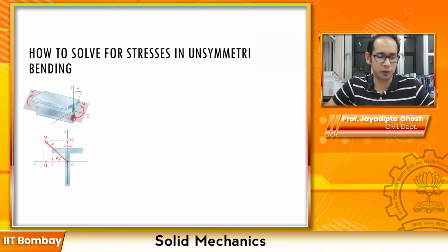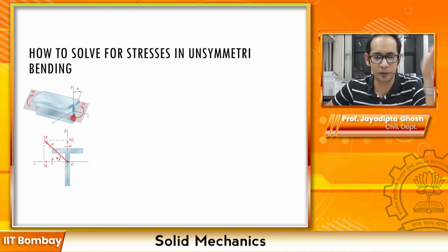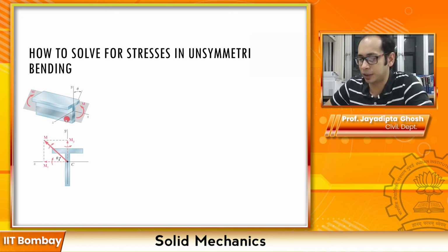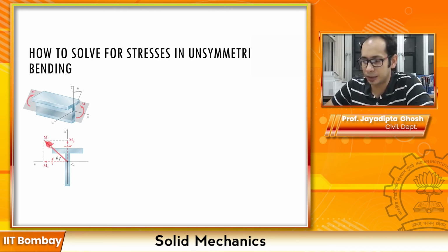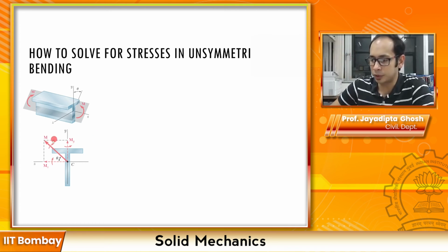The one which I was showing you with the styrofoam is a rectangular section, but as you know, the formulations we have derived are valid for any prismatic section. So now if I have this moment, this is the symbol for the moment. The moment is acting about this particular line over here. Again, this arrow is the thumb, where the thumb points, you're curling your fingers, and this is the way your fingers are curling over it.